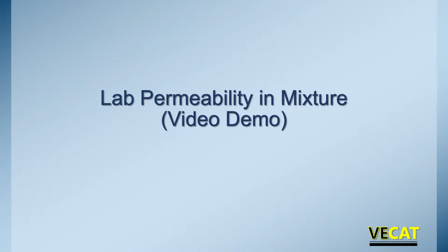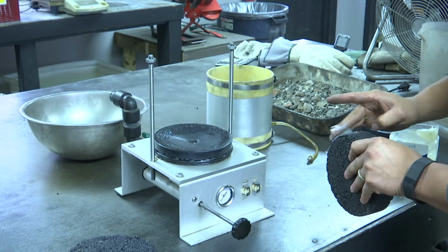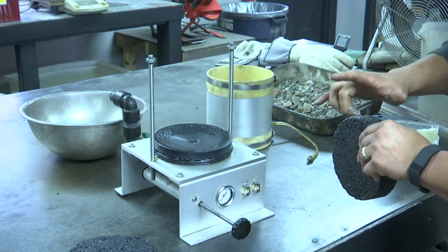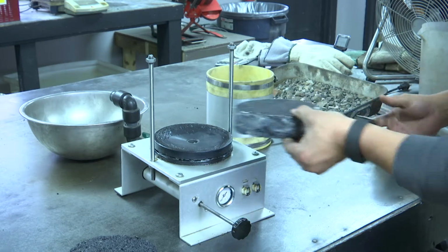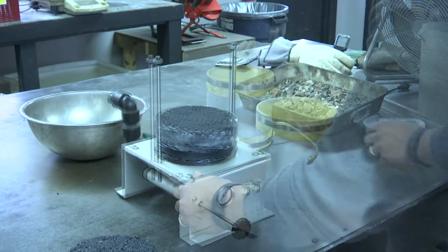Here is a demo video to show how this works. All right, the technician is applying the Vaseline to the outside circumference of his sample. You do not want any on the top or bottom. That would impede the water flow.